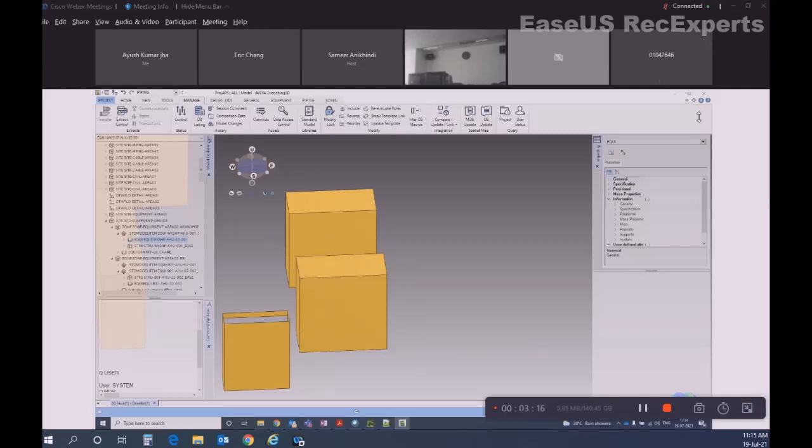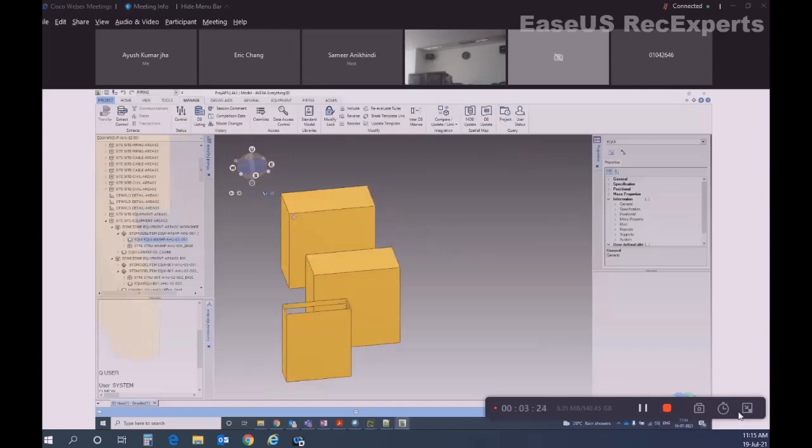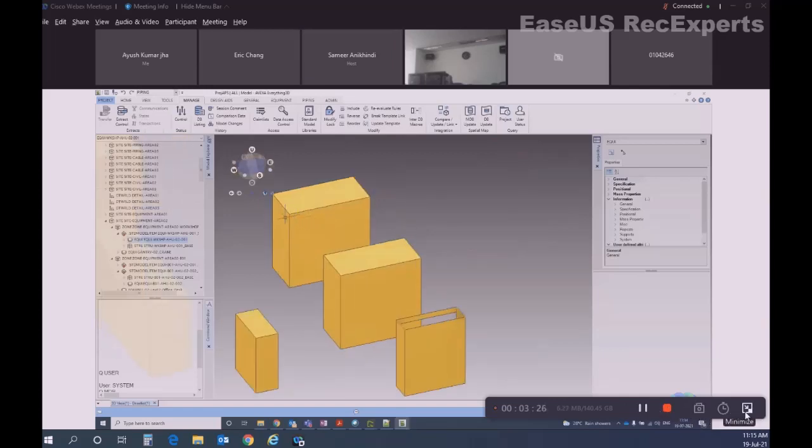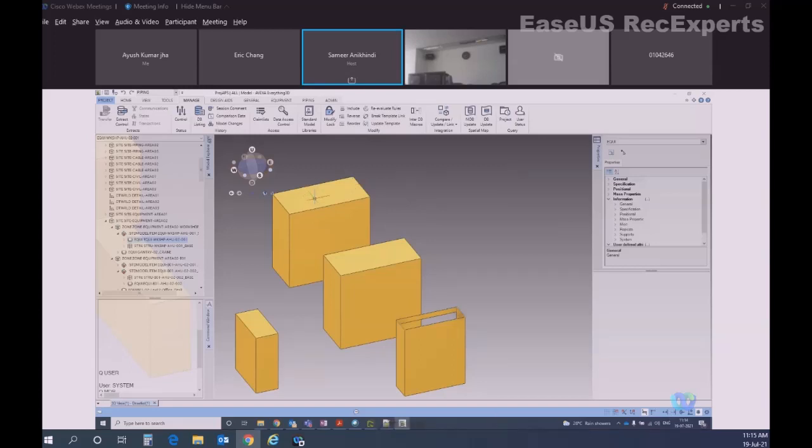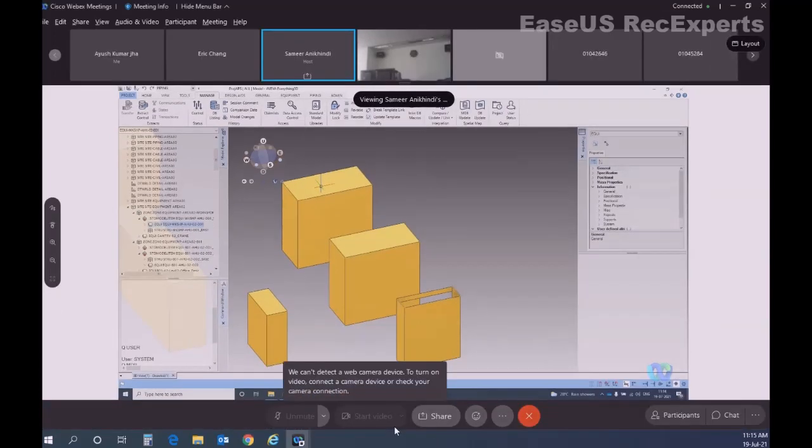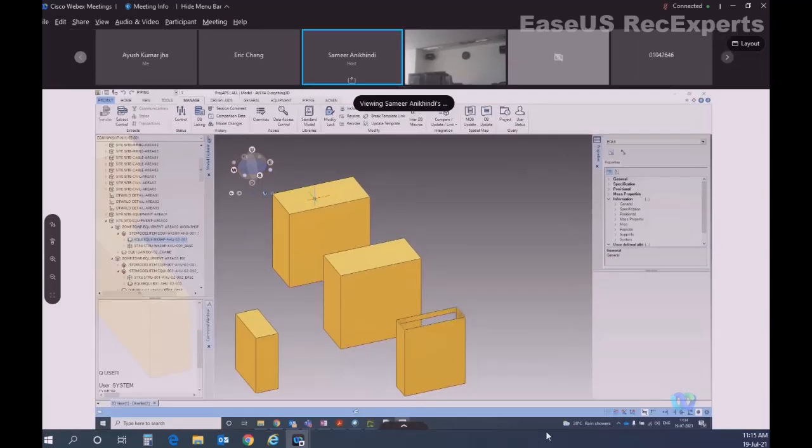Again, how to shift between relative and absolute. So relative and absolute: first of all, the first point will always be absolute. If the input is asking for more than one point, then only that relative and absolute thing will work, because relative is only activated after the first point selection.